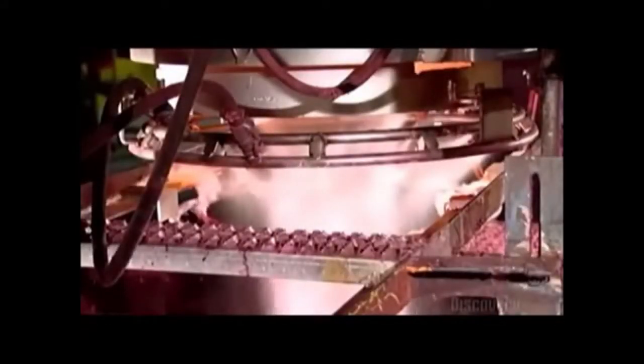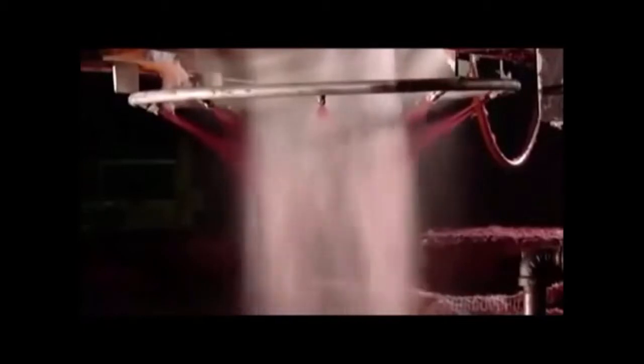The melted glass falls about a meter into a spinning bowl. It's called a fiberizer. The spinning action flings the glass through thousands of holes in the bowl, creating thousands of feathery glass fibers. Gas and compressed air pull the fibers, stretching them thinner. The process is a lot like making cotton candy, and the spun glass even has a similar texture. But the fibers will soon become even more like cotton candy. Nozzles spray them with a polymer glue tinted pink. The now pink and sticky fibers drop into a hole in the ground and amass.